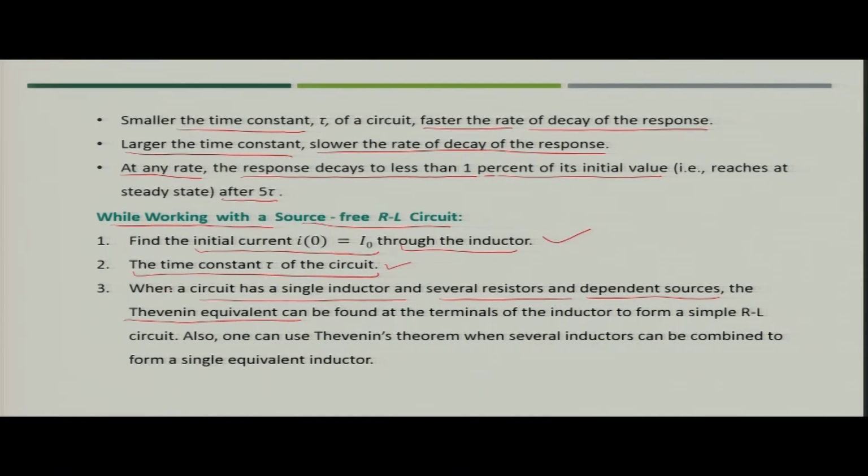So, we will use the Thevenin equivalent at the terminals of the inductor to form a simple RL circuit, or we can use Thevenin's theorem when several inductors can be combined to form a single equivalent inductor. In summary, if we have a circuit with multiple inductors and resistors, we can utilize Thevenin's theorem to simplify the circuit and find the response of the circuit.